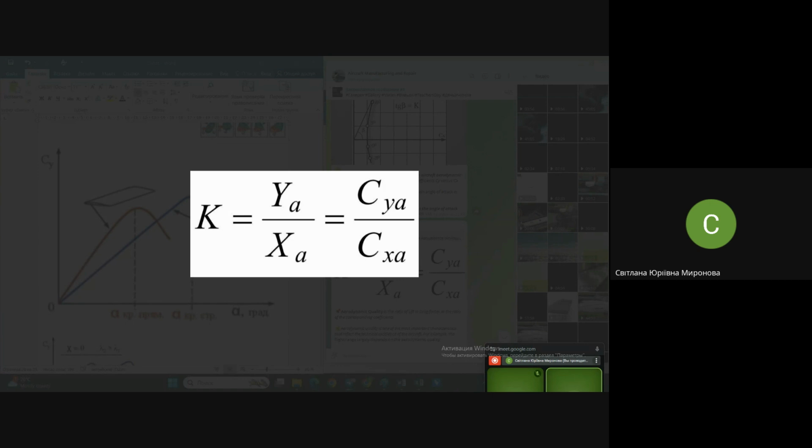Usually we talk about the aerodynamical quality of the aircraft as a whole. I already said, because you've seen in these diagrams, that the aerodynamical characteristics of the airfoil may also depend on the shape of the wing, how these airfoils are located with respect to each other. Next, aerodynamical characteristics may depend on speed. When it comes to drag, it's very important to remember that it depends also on speed, and so on. So usually we're talking about the quality of the airplane as a whole.